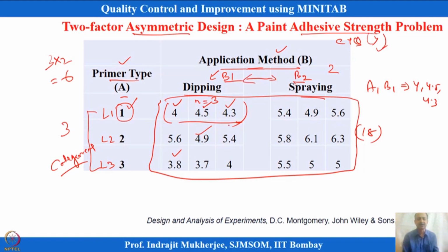So, the factors that we have selected are categorical variables, but the response that is coming out of the process, that means the adhesive strength, is a continuous variable, and you have to remember that in design of experiment, y should be continuous, then we can adopt analysis of variance. For that, these techniques are developed based on those primary assumptions. Okay. Factors can be continuous also, and factors can be a mixture of continuous variables and categorical variables, that is also possible.